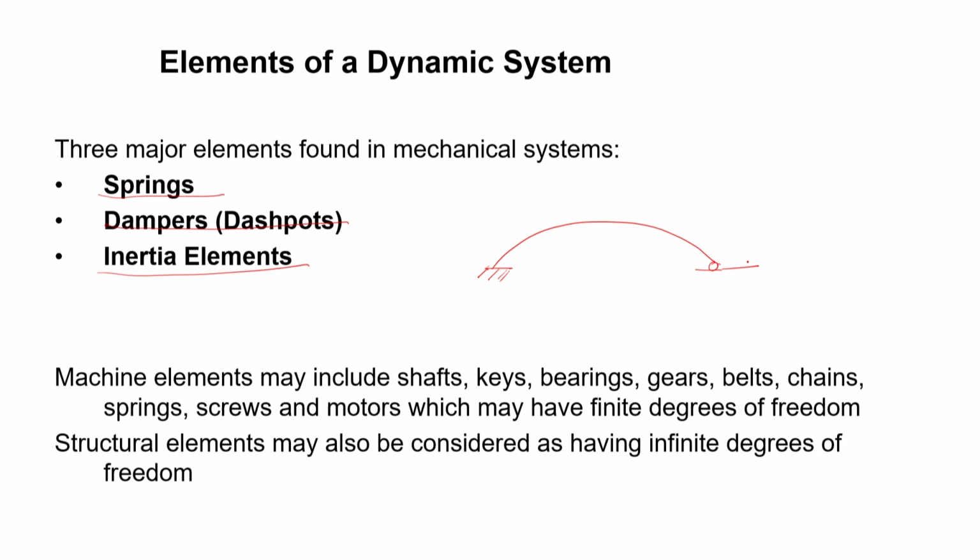Then if I have to design it in terms of springs, dampers, and inertia elements, we can consider that it is going to have not just 1 or 2 degrees of freedom, but a countably infinite number of degrees of freedom in this system, where each element is joined with the other element, and at their intersections the degrees of freedom are present, and these degrees of freedom are constrained by either some springs or dampers or some inertia elements.